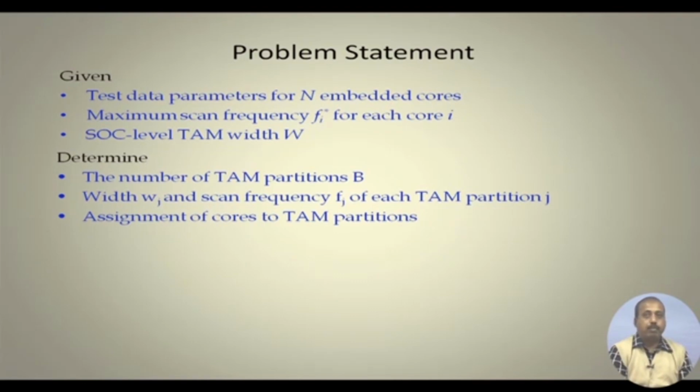level TAM width W. Then we have to determine the following: the number of TAM partitions. So, how many partitions we are doing. Here, interestingly, it is a partition based approach. So, it is no more a bin packing, because there the flexible TAM is not possible, because on the same TAM line it is not possible that sometimes it works at high frequency, sometimes it works at low frequency. So, the frequencies are the same.